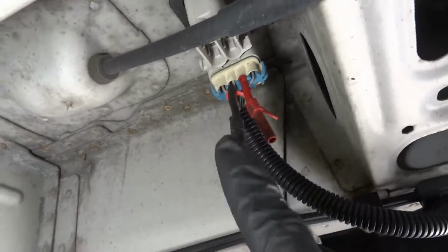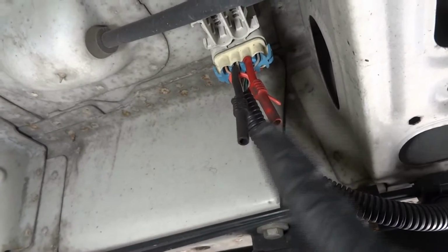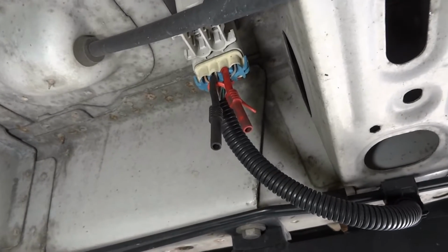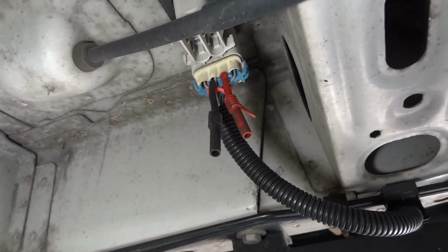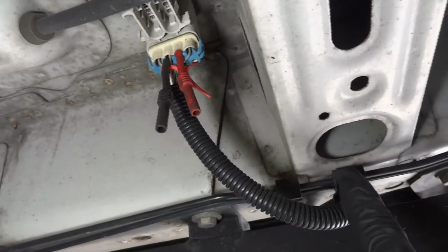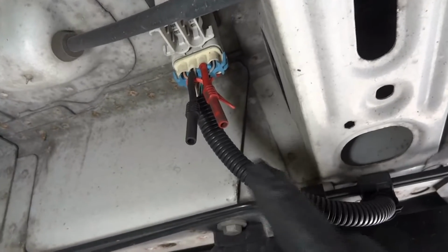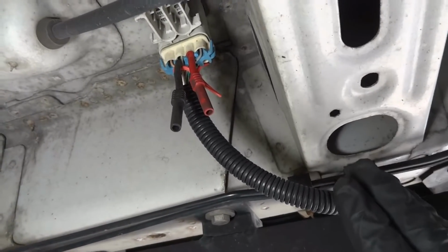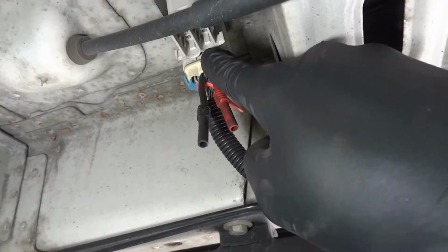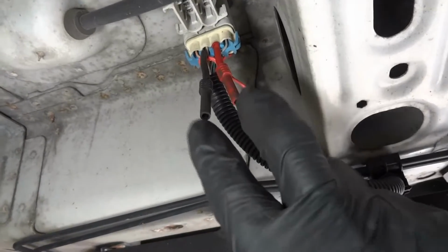So now I'm going to use a test light. I'm going to put a test light between these two back probing tools, and then we're going to turn on the vent solenoid. We're going to close it with the scan tool to see if we have power and ground going to the vent solenoid. If the test light lights, that will tell me that the vent solenoid circuit is good, especially from this connector up to the computer.